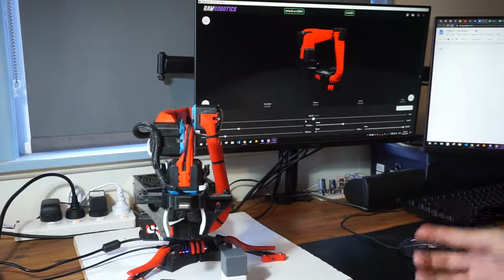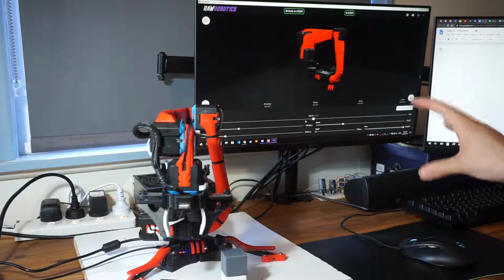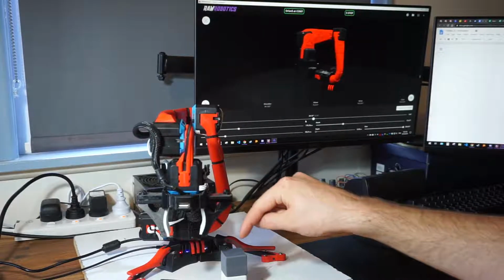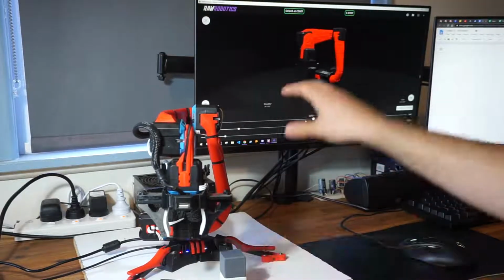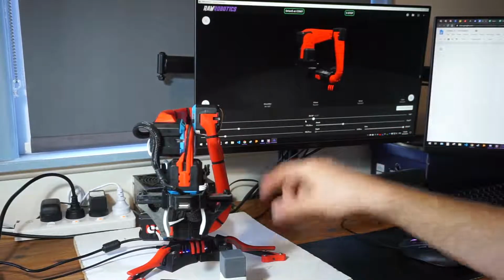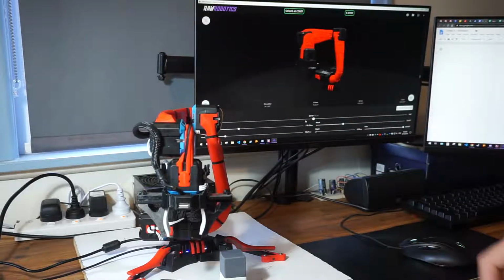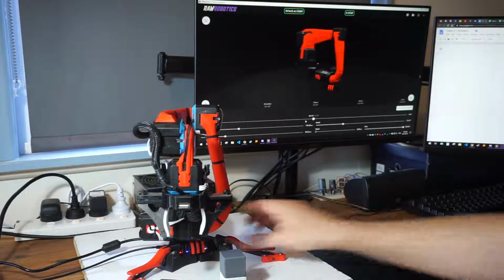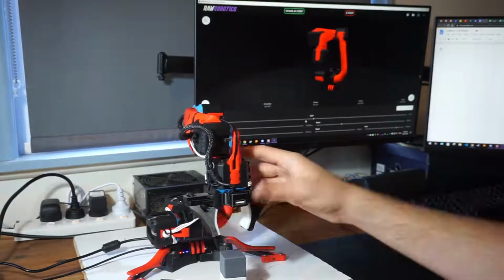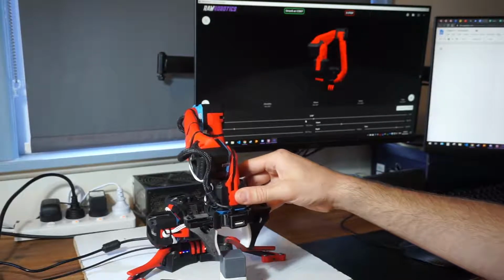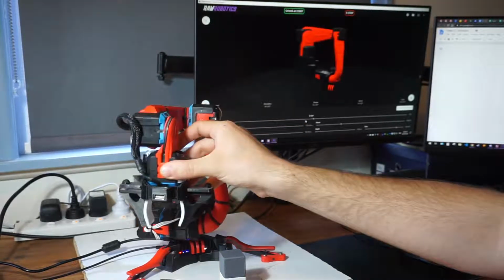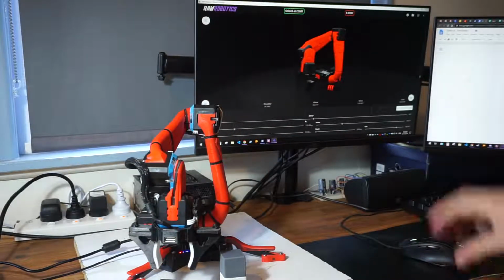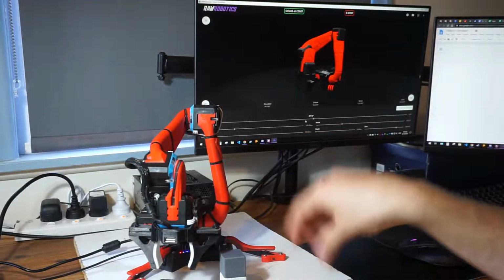It is quite entertaining. The other purpose of these manual controls is to test out different positions and different movements. So now that I have moved a block from here to here, I could go through that sequence again and write down the current positions of all the joints at the key moments. Like at this position above the tower, when we come down, when we go back up, when we move across, and when we go back down. Those 4 or 5 positions, I could write them down, put them into a script, and have the robot do that by itself again and again.